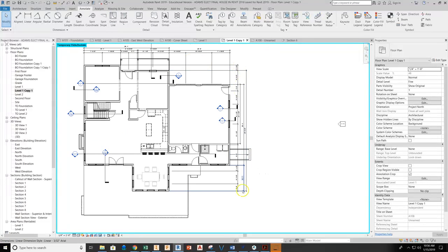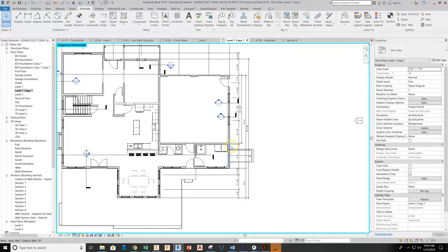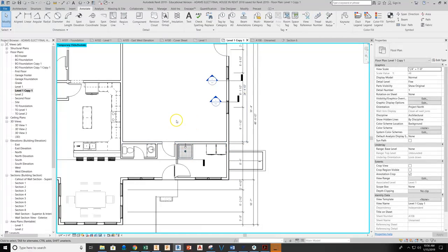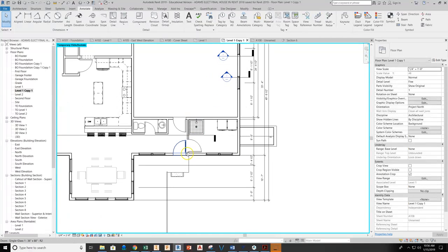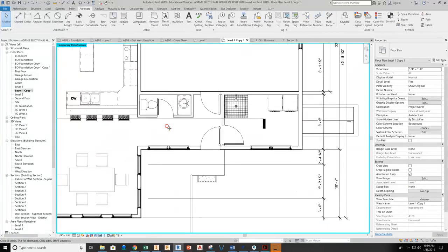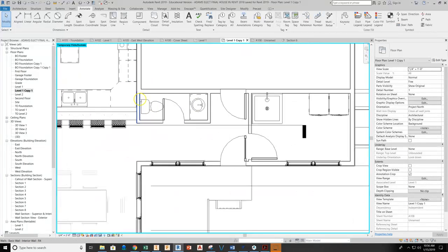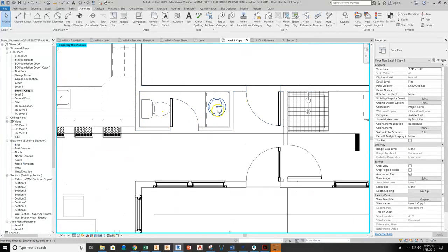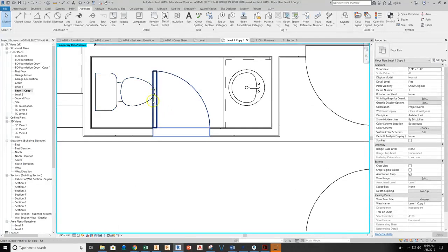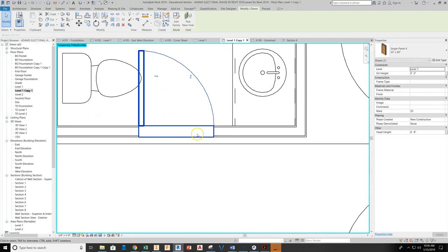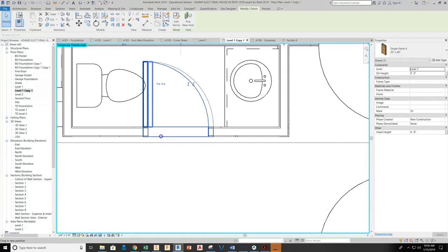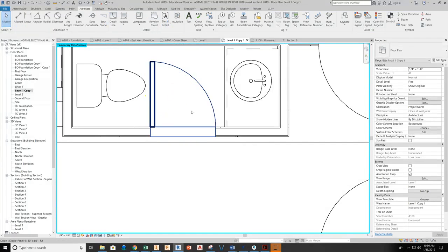So that's external wall dimensioning, where it can actually locate some internal walls. But what happens here when you get into internal dimensions that you haven't been able to pull external dimensions with? So something like this powder room, where actually you can see the doors now running into this commode. This is something where we probably want to move this over a little bit so it doesn't actually hit.